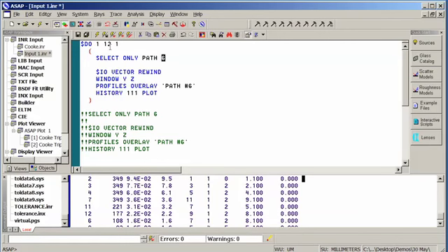I want to use the wildcard to indicate exactly which step of my do loop I'm in, and within ASAP, that's simply the question mark. So each time ASAP goes through this, it will select the path identified within the do loop and then print that information on my profile. Careful now, don't end ASAP. We're going to work on currently saved data, so I just need to run this file.